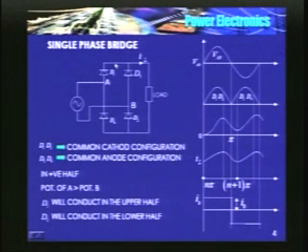In that situation, a negative voltage appears across D1, because potential of A is less than potential of B in the negative half, and cathode potential of D1 is the potential of B. So therefore a negative voltage appears across D1, the diode turns off. Same thing happens in the lower half also. So therefore in the negative half, D3, load, D4, back to source. This is the equivalent circuit.